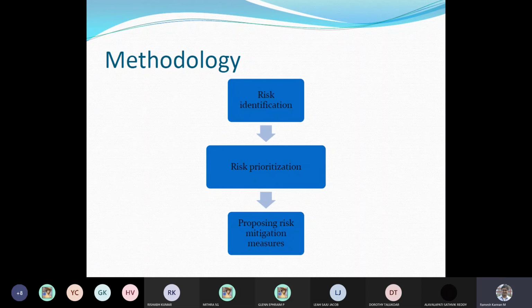Right. But if you ask me whether the final product is good or bad, it's debatable, because when you add too much of retarders, the original characteristics of concrete may not be retained. So it gets altered in the drum itself, and when it is used on the construction side, it may not have as comprehensive a property or sound quality as the original concrete. So there should be a compromise between that, right? So all these things you need to take care of, and those things can be put under mitigation measures.